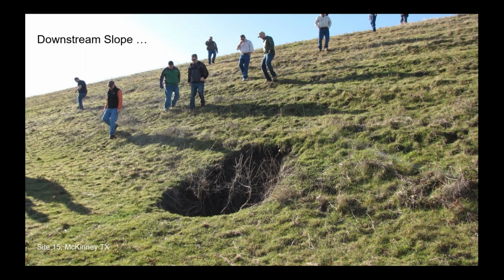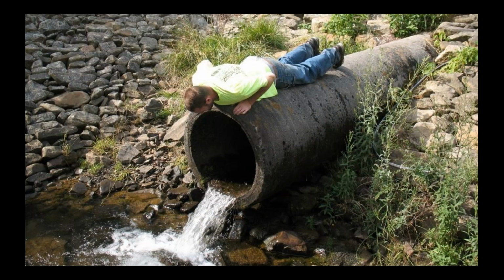If you're inspecting a dam, like I said, you try to estimate where that penetration is through the dam, and not only look at seepage at the outlet. But this is on the downstream slope, and you can see here we have a sinkhole in the downstream slope, and that was a place where that pipe had a defect, and seepage was going in and above the defect and showing up there. So it's really important to inspect these conduits.